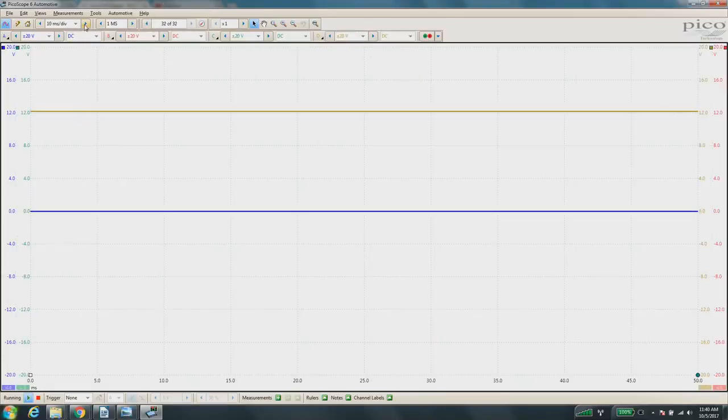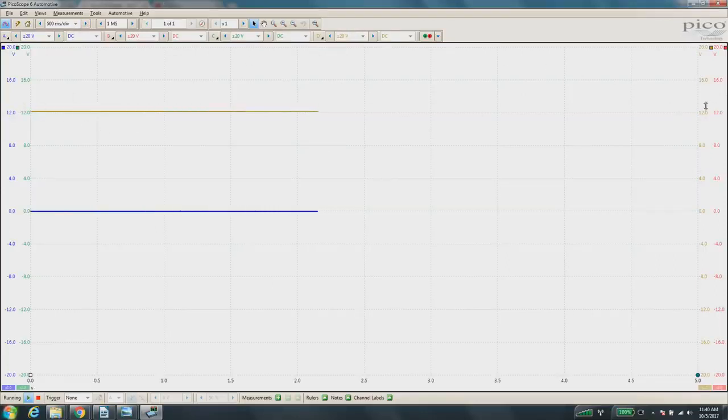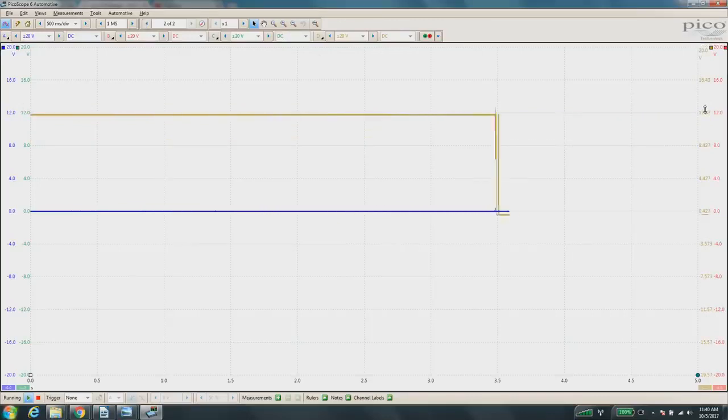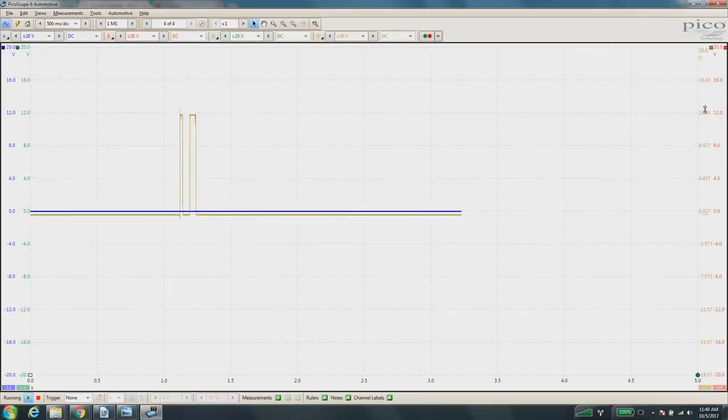Yellow seems high right now. Is the key on, Jim? Yes. Okay, key is on. I don't think yellow should be up there. I might have the wrong signal here because we should be in, are we in park? All right, let's try this. All right, what do we got? I want to see our blue up around that 12 volt line because right now we are in park, so we should be sending, oh wait, still not connected, right?